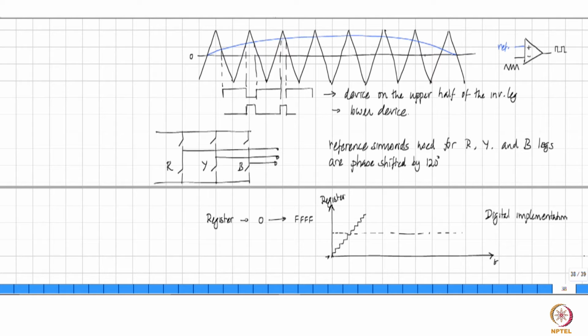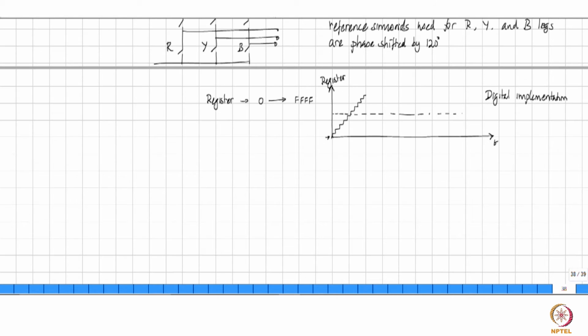But whereas here, the EMF is going to change instant to instant, and therefore you need to know the rotor position instant to instant so that you can relate, okay, if it is at this angle, I would expect that much of EMF given the speed, right? So, therefore, you need, in this case, continuous rotor angle information.